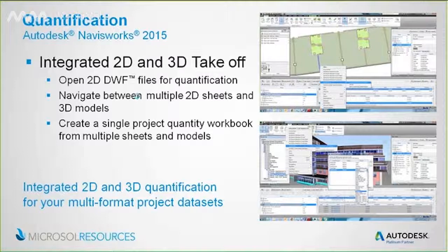But one of the new features that we'll demo, and we'll just go through these three slides and then I'll jump into the demonstration about the quantification, is that you can open up 2D DWF files for quantification. You can use the project browser to navigate between multiple 2D and 3D sheets, and you have essentially a centralized project quantity workbook for all of these, so that you can take off an entire model and see what you've taken off in each of the different sheets.